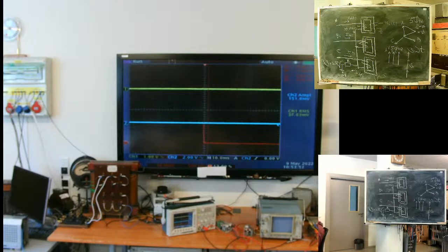At night, when there is no load, the transformer core saturates, a large amount of third harmonic is in the neutral current, but neutral is isolated, so we'll see overvoltage. It's one of the possible problems of distribution networks.